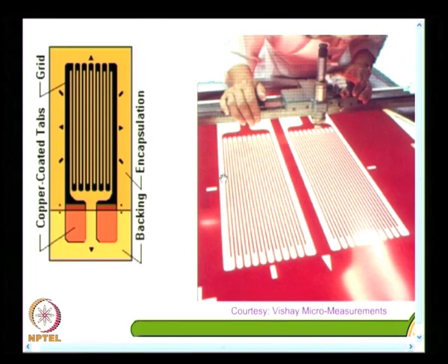And remember, when you look at the foil like this, this is a metallic foil, but when I am going to have a very thin foil, even a thin metal foil is fragile. So, handling becomes very sensitive. If you understand the construction and also the level of measurement that you are going to make, it brings in automatically a sensitivity in you in how to handle the strain gauge.